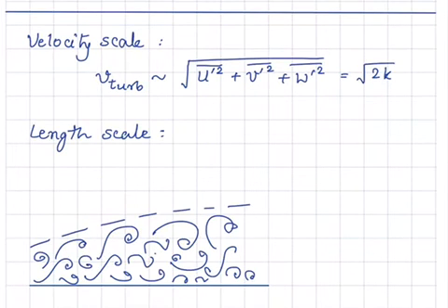An assumption or approximation is that the largest eddies there can be are of the size of the boundary layer itself, the thickness of the boundary layer. So if I call this delta, L turbulent is kind of proportional to delta. Of course, it cannot exceed delta. Turbulence is all inside the boundary layer, but it's of the order of delta. This symbol, which I write as tilde, means similar to, of the same order of magnitude as this.